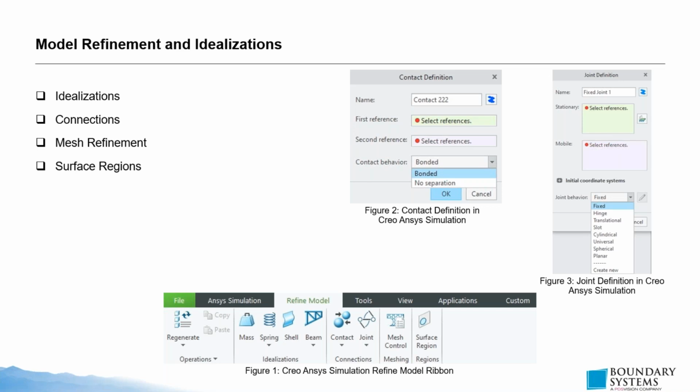To explain a little bit further, we aren't able to yet do friction analysis or any kind of contact analysis. Those are coming in the future. But right now, we are stuck with bonded contact behavior. So things are stuck together, super glued, won't move. We also have a contact definition for no separation, which will allow some amounts of frictionless sliding.